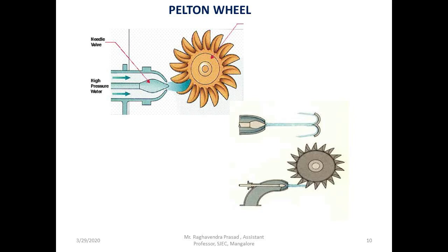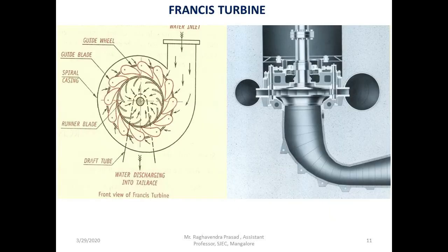Francis turbine. The Francis turbine is a reaction type of turbine. That means water will be filled in the casing all the time. That means all the stationary and moving blades will be in continuous touch with the water always, unlike in the case of an impulse turbine.